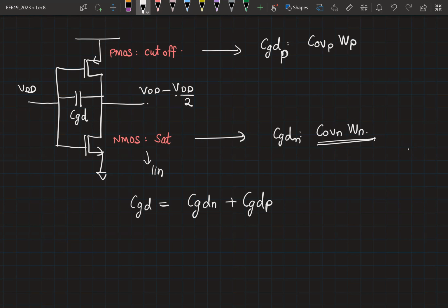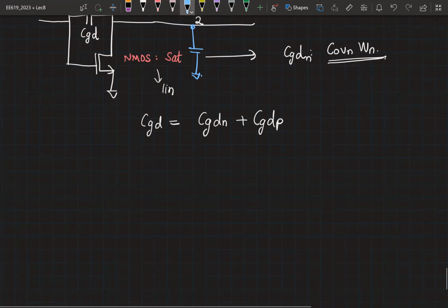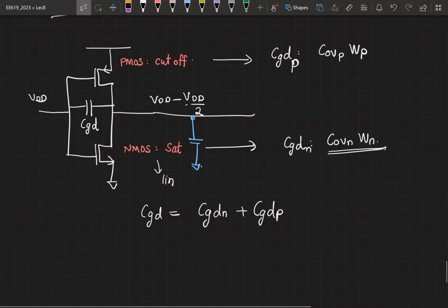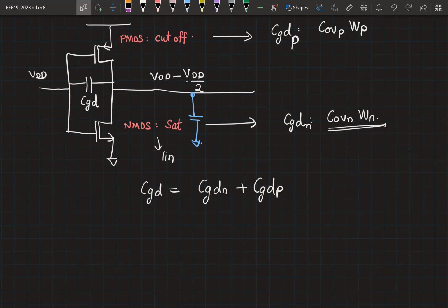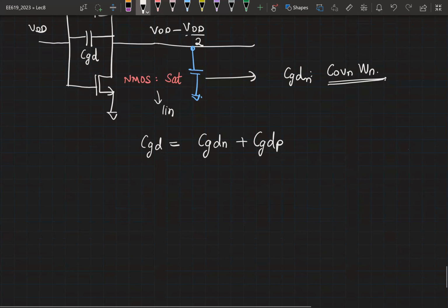But what was our aim? We want to transform this into a capacitance that is connected between the drain node and the ground node. Right? So any suggestions on how we can do that? There are explanations based on Miller compensation, but the definition of gain is very tricky here, right? You say gain is -1. Why? Because for an inverter, that is a little tricky. So I'd like to use the explanation where you retain the same change in charge. Okay. So let's go through that definition.